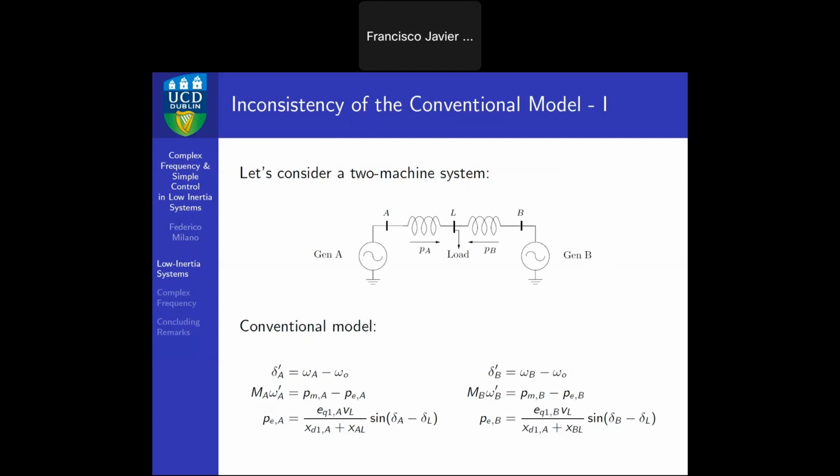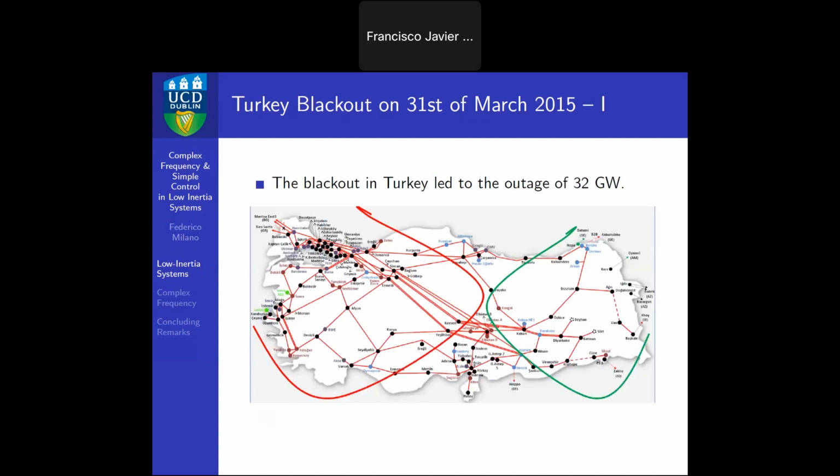Okay, and that was okay, but then since I wasn't satisfied, we got to the complex frequency definition at the end, which, because we were neglecting all the voltage magnitudes and the fact that they interact with the phase angle as well. Well, this is just a case where we show that in fact the frequency is not the same everywhere. This is Turkey, and these two lines indicate the separation of the grid. Now there was a huge swing after that, and that impacted neighboring countries.